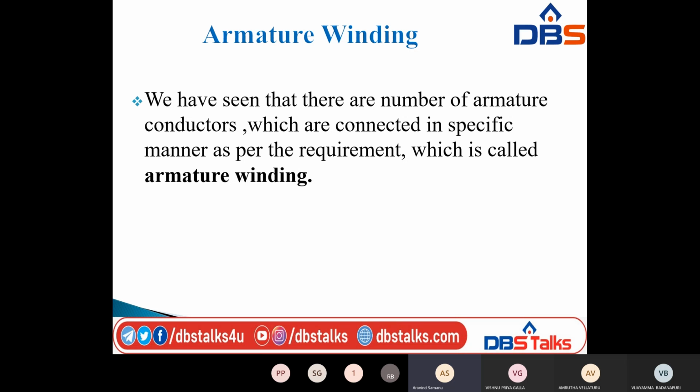You have already seen this in the constructional details of the DC machine. Here we have the armature conductors, which is nothing but the armature winding. Once again, I am repeating the definition of armature winding: a number of armature conductors which are connected in a specific manner as per the requirement is called the armature winding.